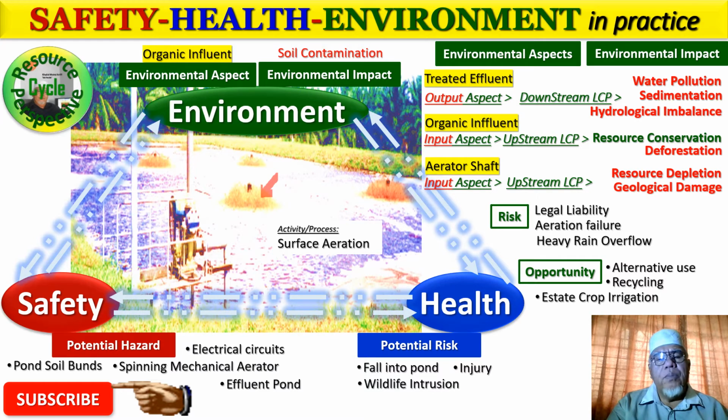When we took a sample from this pond, we found about 4,200 milligram per liter of MLVSS, mixed liquor volatile suspended solids, which is a marvelous population of aerobic bacteria for the decomposition of all the organics from the effluent. This effluent is organic because it is from a palm oil mill, and nutritious, with lots of nitrates and also phosphates.